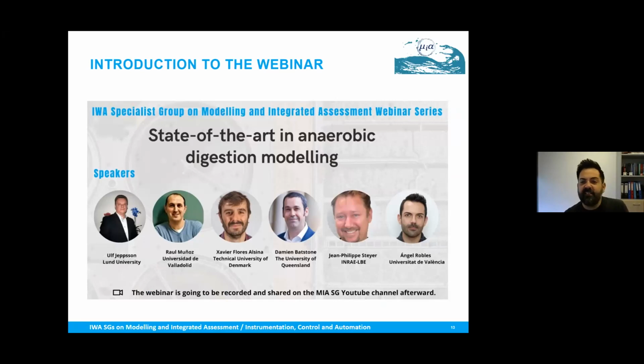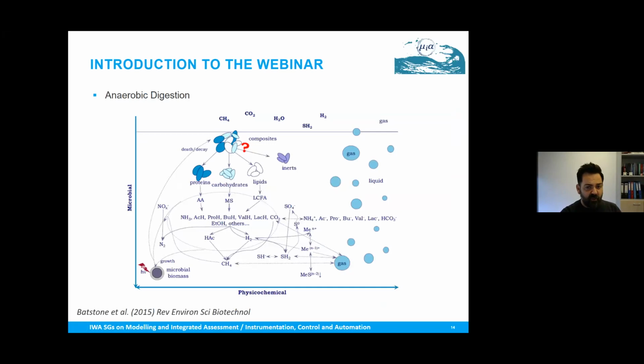So let's start with today's webinar by introducing very quickly anaerobic digestion technology. As most of you know, anaerobic digestion (AD) is a multiple step process in which complex organics are converted to the most oxidized forms of one atomic carbon, that is carbon dioxide and methane.